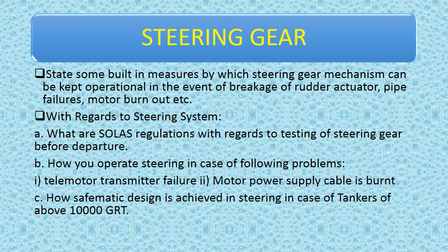So it's another question. With regard to the steering system, you have to explain what are the SOLAS regulations with regards to the testing of a steering gear before departure. So, 2 hours before departure, what test is being carried out with respect to steering. How will you operate steering in case of the following problems? Telemotor transmitter failure, motor power supply cable is burnt, and next one is how safe-matic design is achieved in steering in case of tankers of 10,000 GRT. Okay, so this is also the completion of the steering questions.